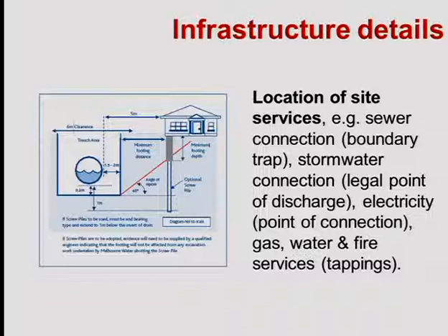So if I am generating load at 45 degrees, may I demonstrate on you? So here's a pipe. Here's a new building generating load. What happens to the pipe? Because it's taking my load. Okay? So you can't build on any area where your load transference is going to impact on a service or impact on another structure.